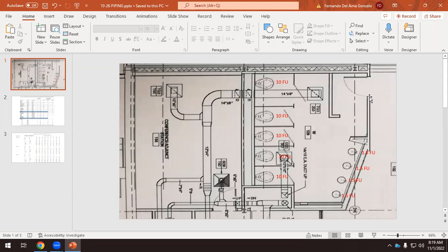If you have stairs, the horizontal part of the stair is 1 foot. So there are things that, when you're reading plans, you can use as measurements. And yeah, you can make a mistake of 1 inch, 2 inches, but nobody will notice. So if we have this door, this is around 3 feet. Depending on the layout of the pipes, I can get by with that. And now, what's the layout? I don't know. So something has to be good enough.